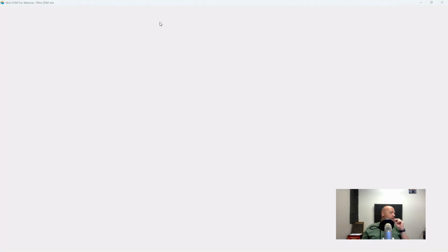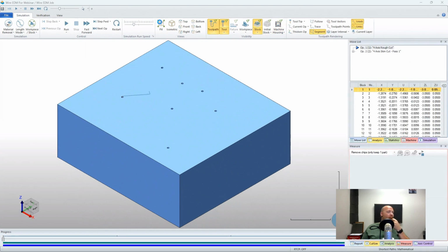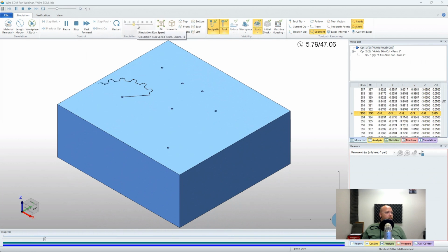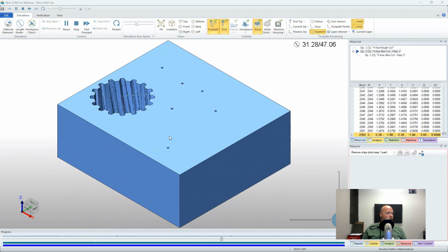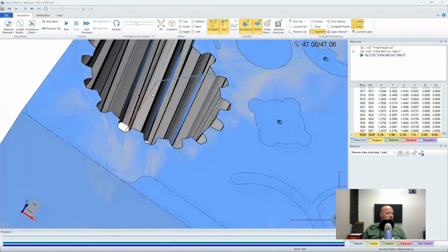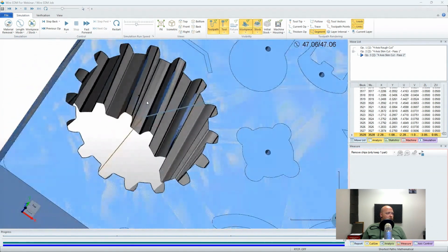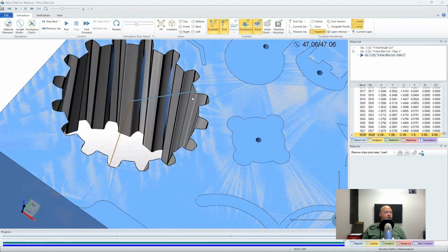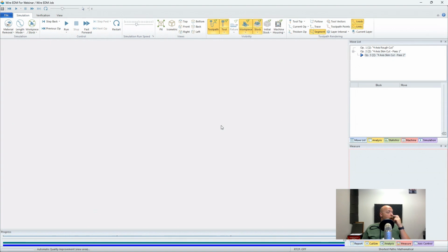Because we might not actually need the sync lines now. Well, we'll say run. We could speed that up a bit. And we'll compare that to our workpiece again. That's a little closer. Looks a little better. We can probably do better, especially in those corners. But those are at least now tapering the right way. But again, it locks that angle in. If you're off on your start, you're going to be lagging behind on the bottom of the cut.